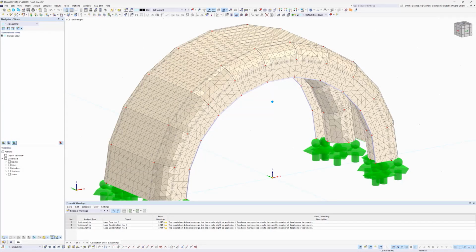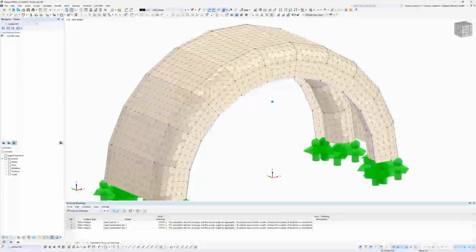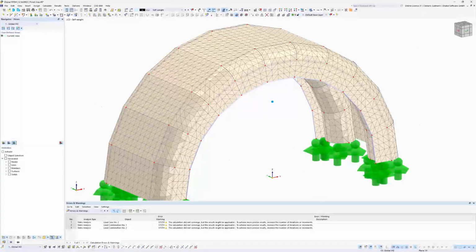So you can model, of course, contact with friction in RFEM, but in reality you would stretch this membrane over the tubes, and there would be in circumferential direction high deformation that would require that mesh elements reconnect dynamically, and that's not easy to model.